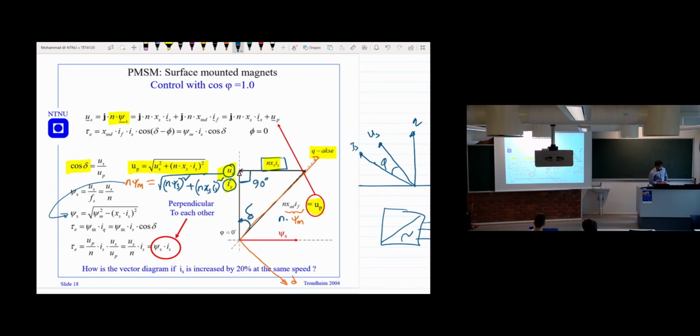So what is it saying to us? It's saying that the stator flux, this psi s, also depends on this current. This means if you increase the current, it is reducing the stator flux, right? Since this is minus here, if you increase the stator current, it is reducing the stator flux there. So this is the one observation that we notice.